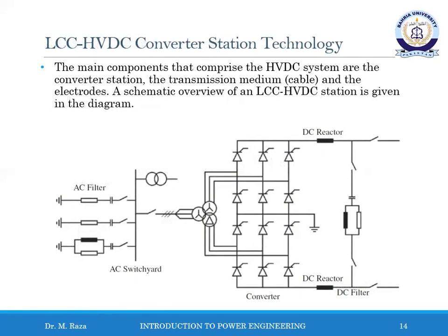The thyristor valves of the converter have to perform the following tasks: connecting AC and DC sides, conducting a high current up to 5 kiloamps, blocking a high voltage up to 8.5 kilovolts, controlling DC voltage via the firing angle, and operating fault tolerant and robust.